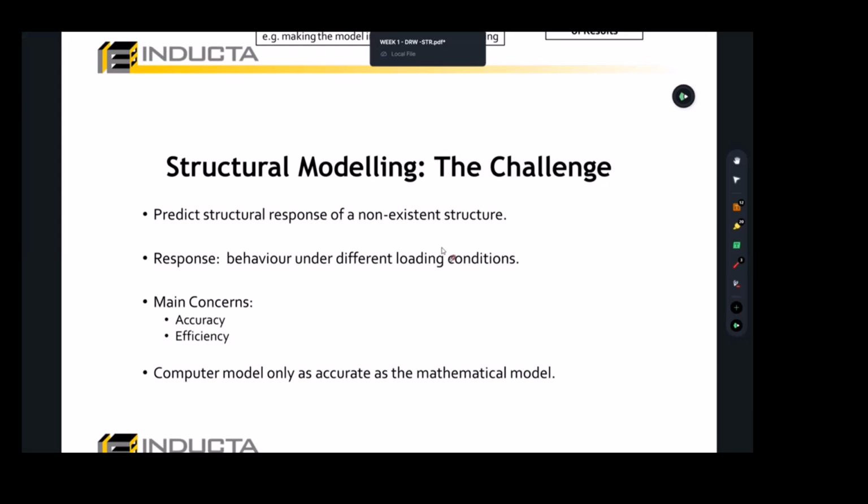If your building uses a block wall, it's different than if your building uses precast panels, because precast panels have simple mechanical bolt connections, but block walls can be well engaged into the structure. So there are challenges in terms of predicting the structural response. That's why there is always a team, with different engineers checking on each other.